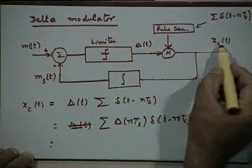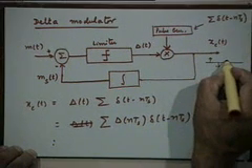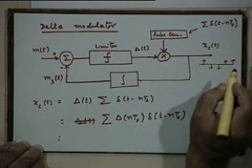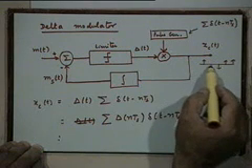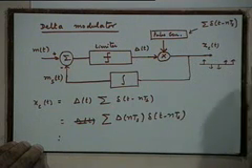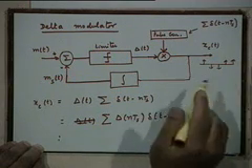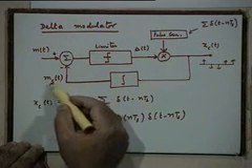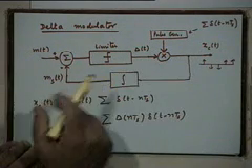Okay, so x sub c, let me just make a comment here. This is a series, as you can see, the nature of this signal. Can you see what is the nature of the signal? It's just a series of positive and negative impulses, right? Because depending on what kind of value δ(t) has, the output impulse will be either positive or negative. So the final output is a digital stream, a binary stream, a two valued stream. And that's what you wanted. You wanted a binary stream. You got a binary stream. From this binary stream, you are generating this reference signal m sub s(t). So we need to understand the nature of this reference signal to understand what is happening, right?